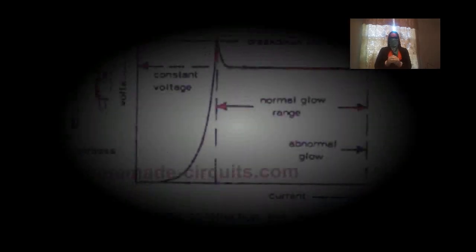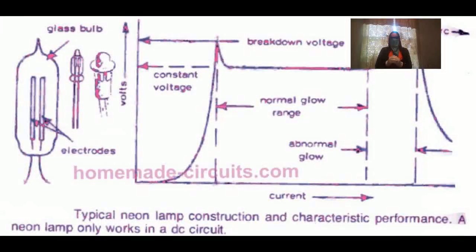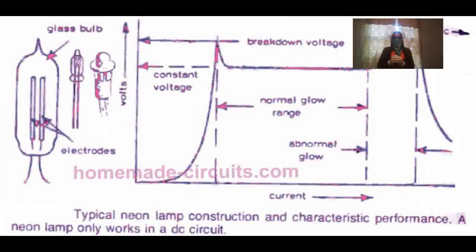Glow lamps. The glow lamp is very similar in construction to a neon lamp. It consists of two electrodes inside a short glass tube filled with neon or argon. The electrodes in a glow lamp are quite close in comparison to the neon light. Consequently, a glow lamp does not require the same high voltages required in typical neon signs.